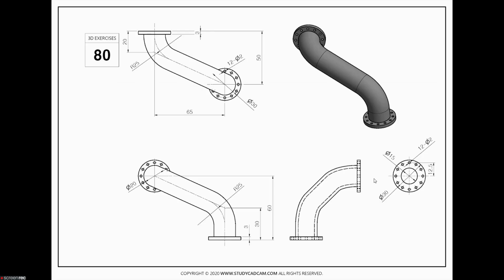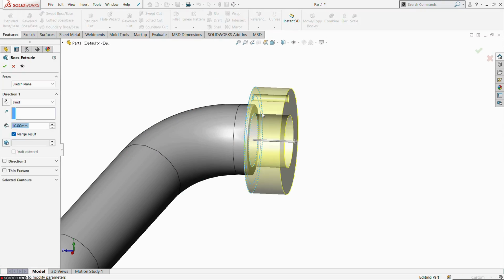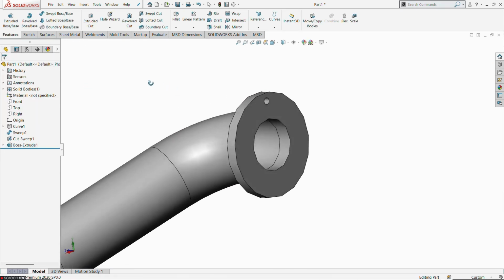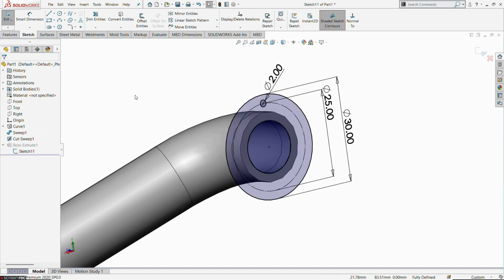Afterwards, we can either create a solid body by using that, or we can simply use this profile also to make the overall solid part within the sketch profile itself. Look at it, using extrude boss with a thickness of 3 mm projected on the opposite side. Now look at the small circular pocket. It is also projected on the opposite portions to create a solid body.